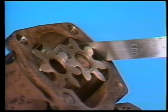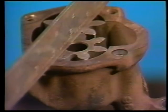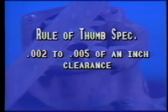To check an oil pump, you must measure the clearance between the oil pump gears and the housing, and between the oil pump gears and the cover. All components must be cleaned before any measurements are taken. When measuring the clearance between the gears and the cover, use a straight edge. Always check the manufacturer's specification for the acceptable clearances. However, as a rule of thumb, there should be between 2/1000ths and 5/1000ths of an inch clearance.